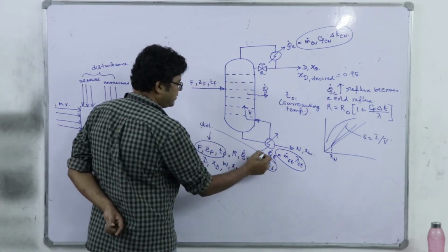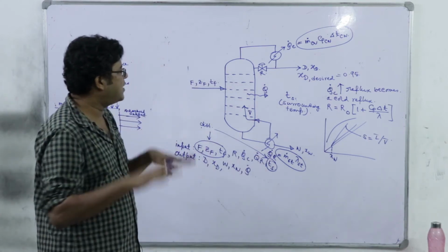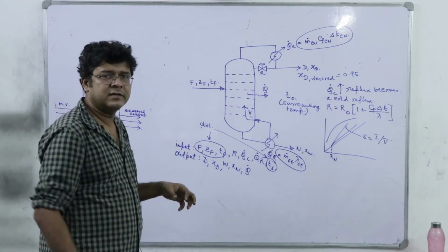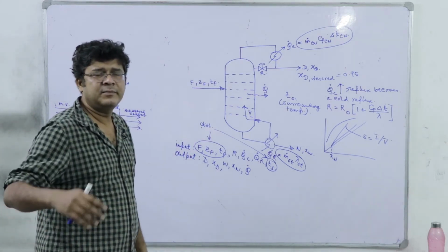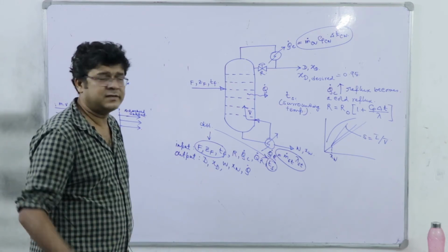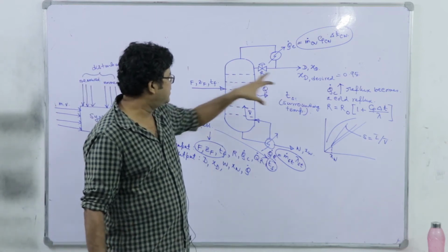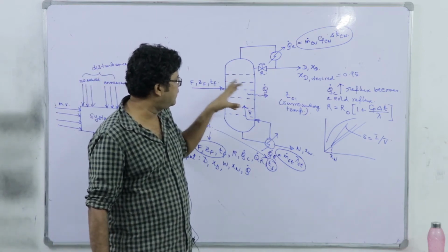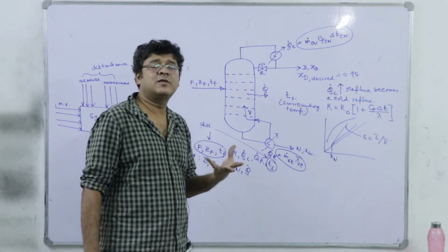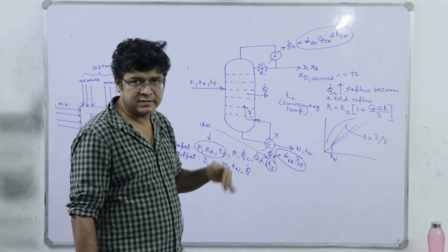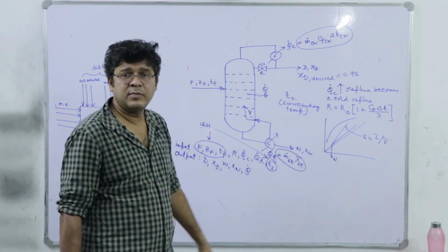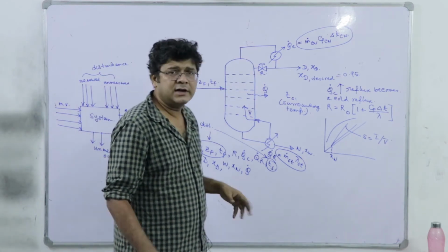Because let us say because of a weather change, there is a drop in TS, right. Initially it is 30 degrees. Now it has dropped to say 25 or 26 degrees. So the thermal gradient between the column and outside is going to increase, because TS has dropped while the average column temperature remains the same. As a consequence, this Q dot will increase.